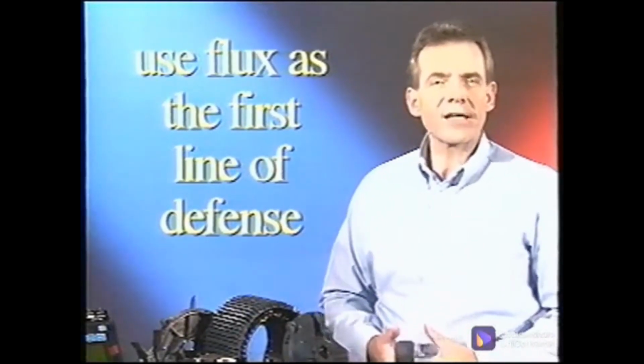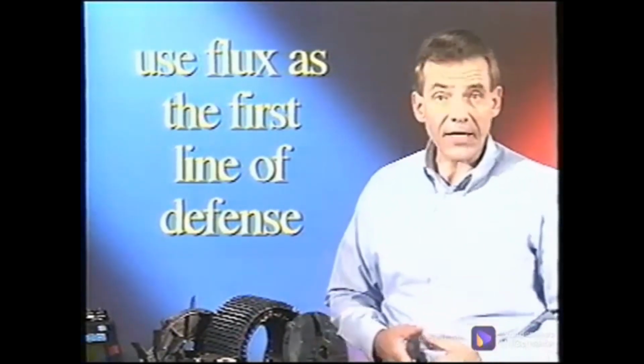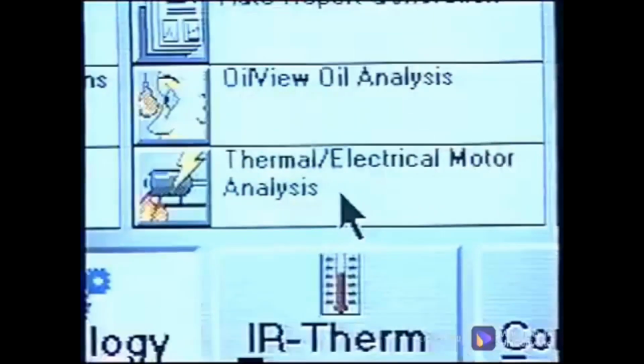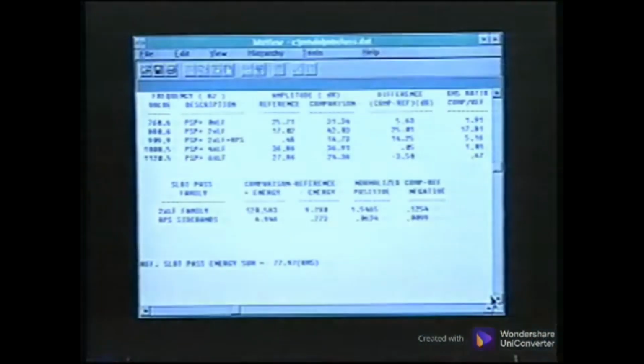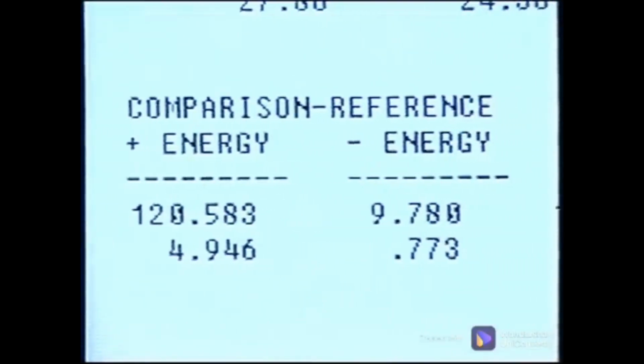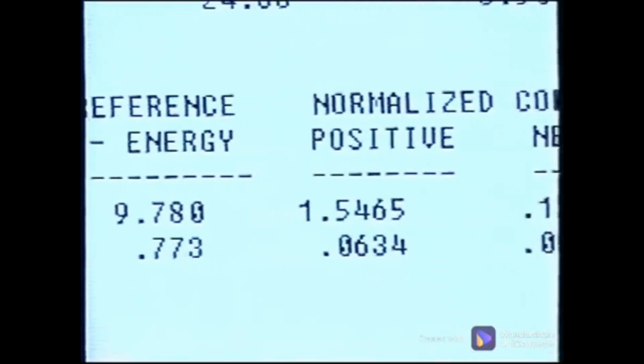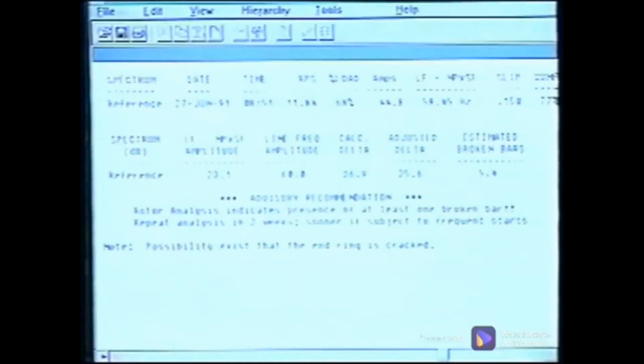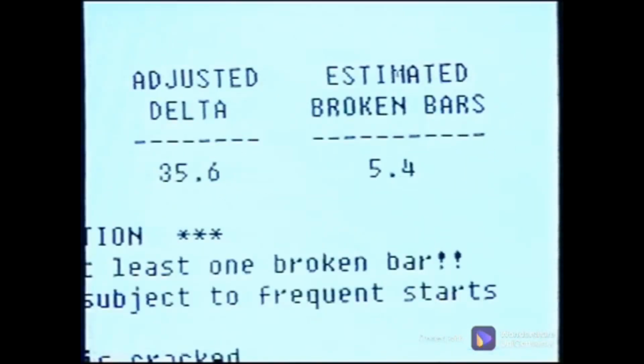These measurements can be analyzed one by one, or the analysis can be performed by a computer software program, such as CSI's MotorView 2, which automatically scans the data for families of peaks, individual peaks, and sidebands, as well as the loads on the motor. The software performs the analysis calculations and generates a report estimating the rotor and stator condition along with recommended actions.